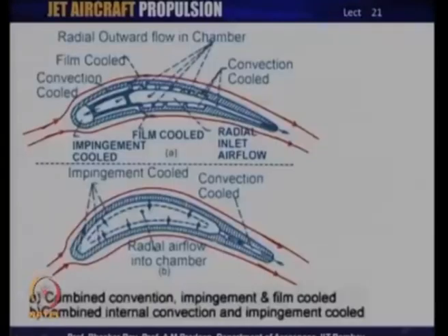This is a kind of typical turbine blade cooling that is used. This is a typical turbine blade. In the front here, you can see the impingement cooling technology, which is used to cool the inside of the leading edge, which, as I mentioned, is a hot spot, and then you have the film cooling, which oozes film on the blade surface to create a protective layer over the blade surfaces.